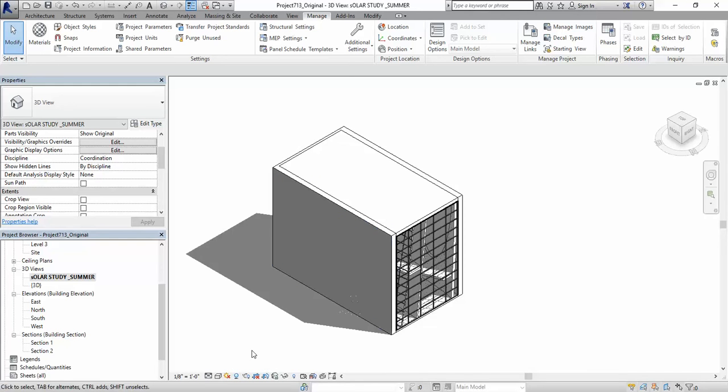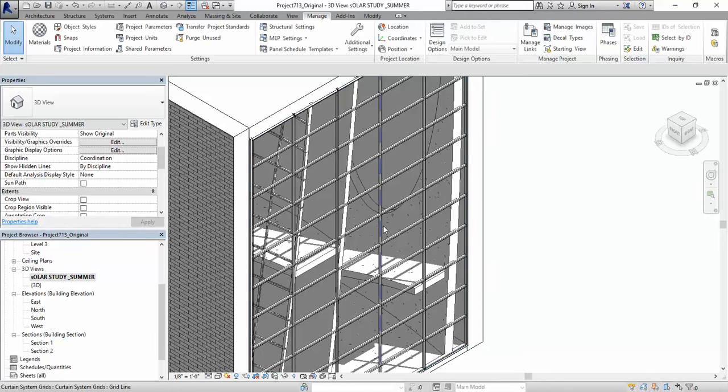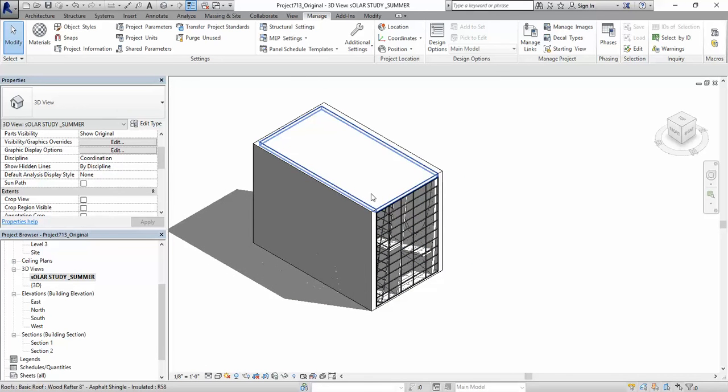So I will just click here, and already I will get a very first understanding of the shadows that this building is casting to the ground, but also why not shadows in the interior of the space from one wall to a slab. In order to get a better understanding of the interior shades, I could very fast override the visibility, the transparency, options from the visibility and graphics menu.